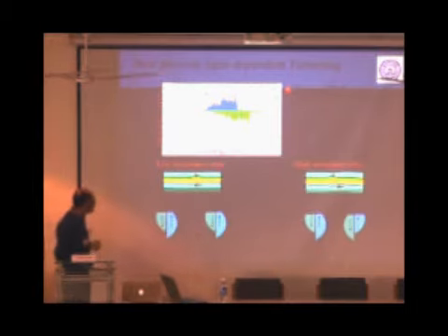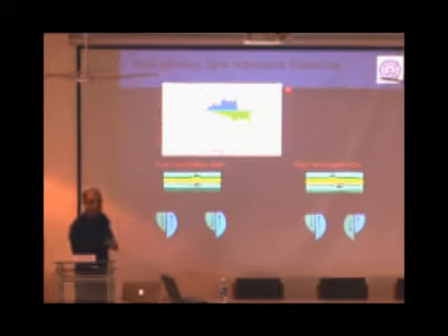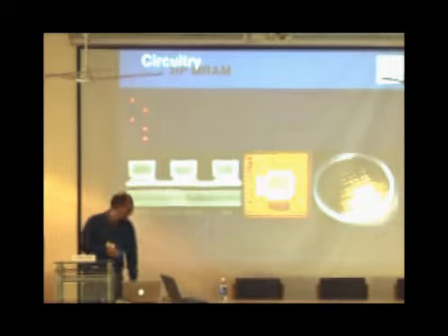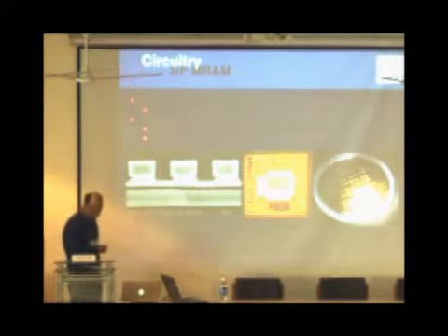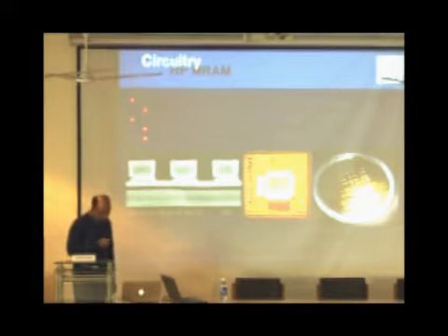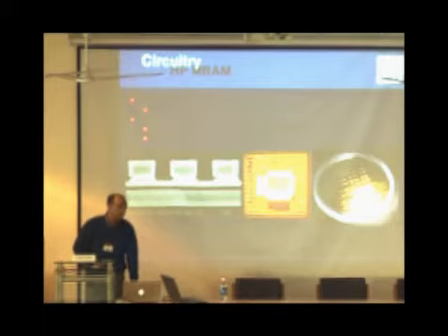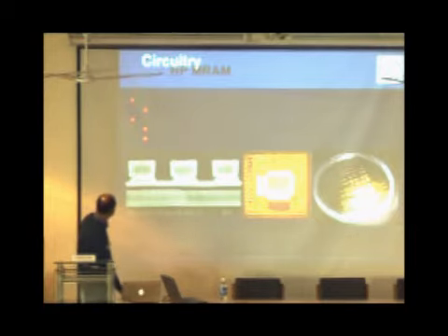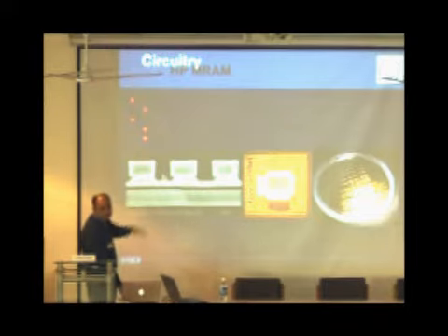So nowadays they use what is called spin dependent tunneling based MRAM. This essentially uses a ferromagnet, insulator, ferromagnet tunnel junction to store the bit, and I'll give you some examples. So this is from where I used to work. This is a 3-conductor MRAM. We demonstrated 1 gigabit MRAM in 2003. So what you see here is a single layer of MRAM, and it's actually designed to be sandwiched between the copper damascene layers at the interconnect level.